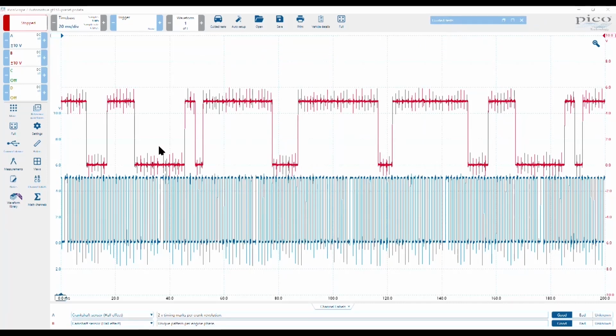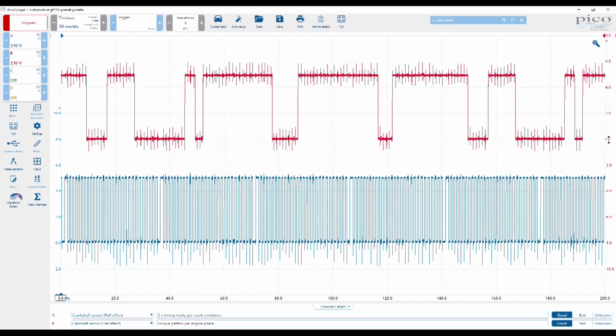So the point here is we've got two signals. For those of you that aren't aware, the red signal is our camshaft signal, and it does show you down here, and the blue is the crankshaft. I'm just going to separate these a little bit, just makes it a little easier to see. Now it tends to be easier to look at the crankshaft position sensor first. So we always have this gap, from here to here, and this is one rotation of the flywheel, and that is actually the gap that you see on the flywheel, and I'm going to show you a little example of that shortly.